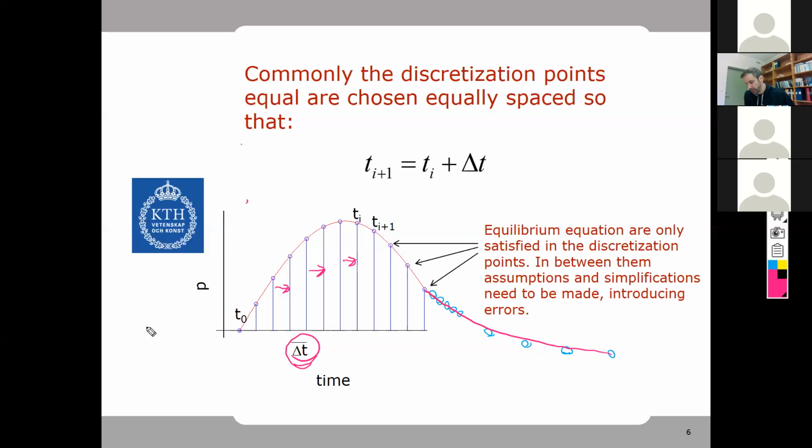So for the exact moment of the explosion, if we had an explosion right here at this point, then everything after the explosion we would want to calculate with an extremely small delta t. But after this time has passed, we can go back to our larger delta t, because of course it takes time for the computer to calculate each one of these points. It doesn't take much time, but it takes some time. So if we choose a delta t that is too small, our calculation will be more accurate, but it will take longer.